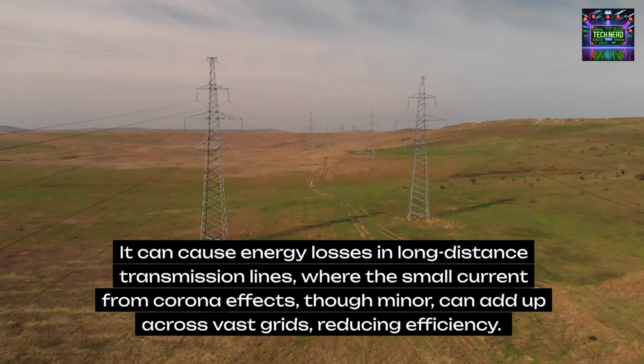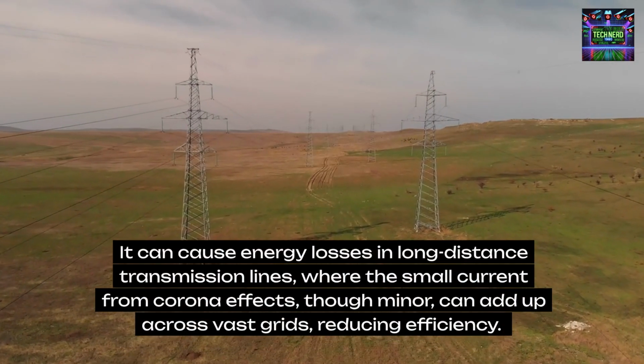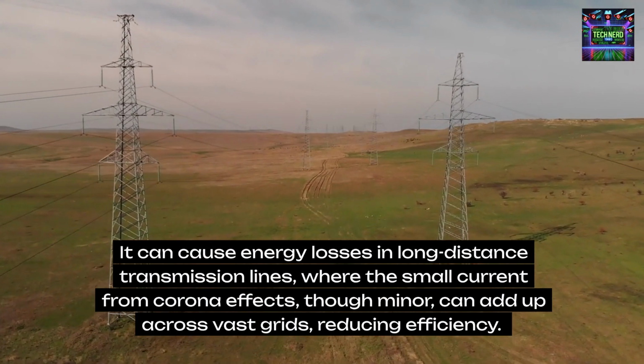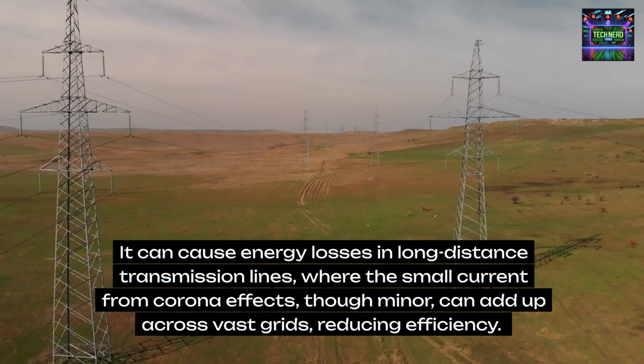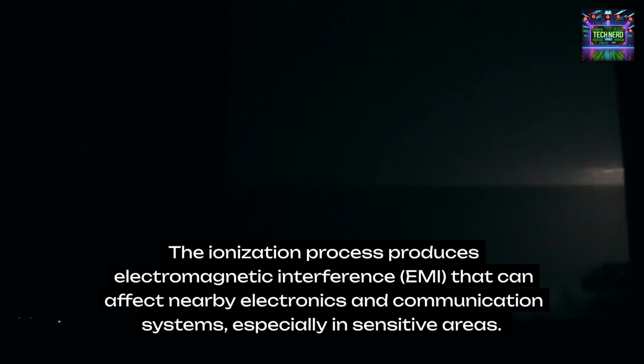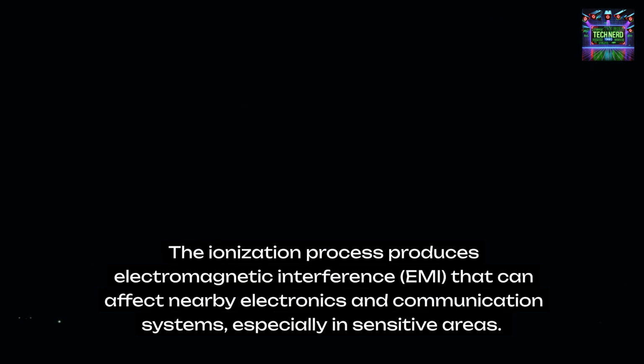It can cause energy losses in long-distance transmission lines, where the small current from corona effects, though minor, can add up across vast grids, reducing efficiency. The ionization process produces electromagnetic interference, EMI, that can affect nearby electronics and communication systems, especially in sensitive areas.